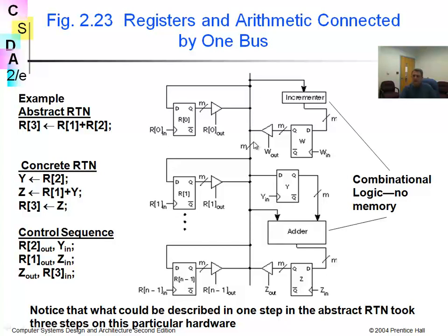And you have a bus. The input from this bus is an input to each one of these D flip-flops. Also, the output of each one of these D flip-flops goes to the bus through this tri-state gate. This tri-state basically controls it, right? If there's an input here, I close all these tri-states, so none of the outputs goes to the bus.